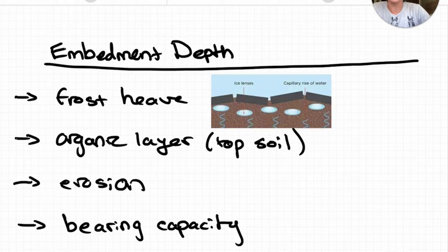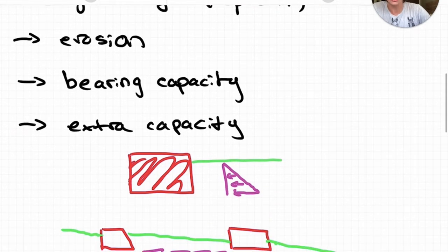So regarding extra capacity, for example, ramp wall and extra access ramp embedment should be minimized to reduce excavation while maintaining full bearing capacity to reduce the risk of settlement. However, while the same trade-off occurs with anchor embedment, a shallow anchor will reduce the ability of the anchor to act as a shear key, which is not considered, as well as it will reduce skin friction or sidewall friction capacity of the anchor. Remember, we ignore the top 30 centimeters of soil for sidewall friction.